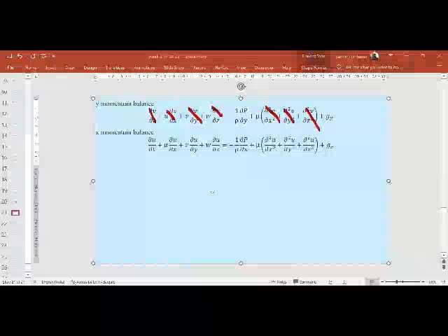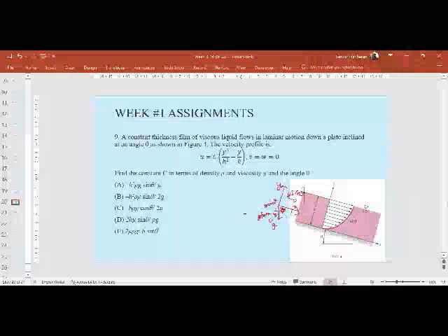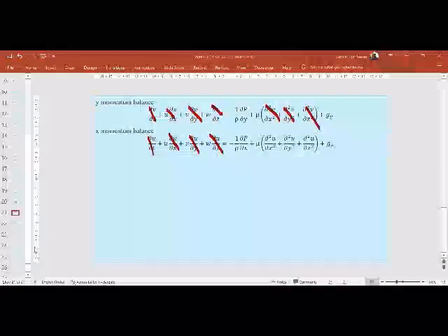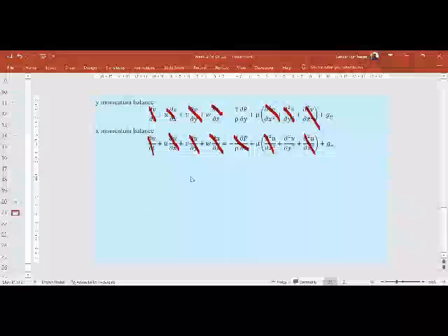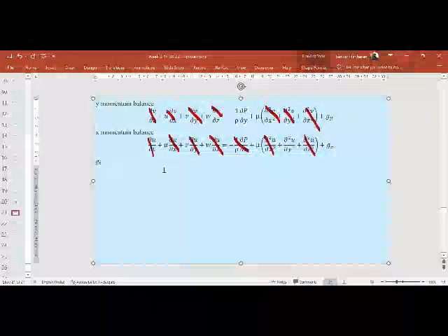So yeah, we have to neglect the pressure gradient since the flow is just due to gravity. So we can neglect the pressure gradient over here, and dou square u by dou x square, since u is not a function of x, will go to 0, and dou square u by dou z square, u is not a function of z, again will go to 0. So we just have to equate these two terms, and what we need to understand here is that the gravity term in the x direction is in fact minus g sine theta, where theta is the angle at which it's inclined.